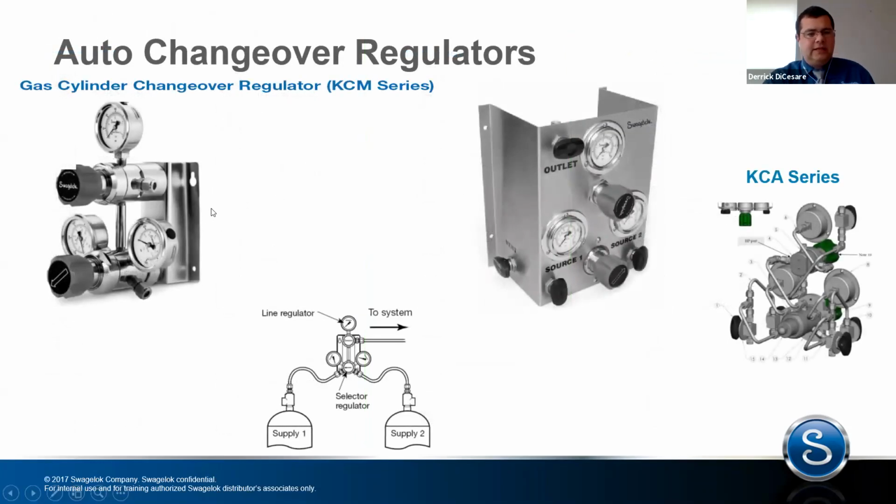I want to talk real quick about the KCM, the changeover regulator. The intention with this is to allow you to hook up 2 cylinders and allow continuous flow to your system. So it allows your primary supply, or supply 1, to bleed down until about when you would want to change it over. It could be 500 PSI, it could be 250 PSI. When it reaches that threshold, the regulator automatically switches over to your second supply. So you don't need to have a technician situated there, waiting for the cylinder to deplete. It's going to automatically change over from supply 1 to supply 2.